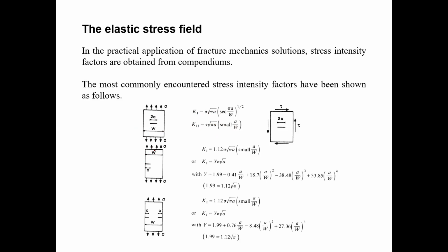And if it is a tensile load but a surface crack, you can see the location is different. Normally we will get the crack length as a. In a center crack, the crack length is called 2a, and normally they give us 2a. So you need to get a, half of this length. But here, the total length you will consider as the crack length. With the diagram, you can easily identify that.